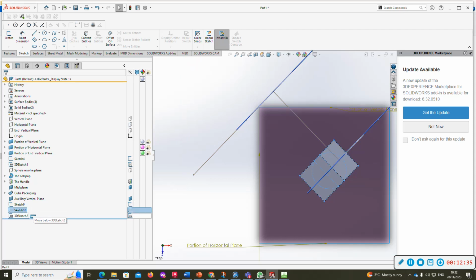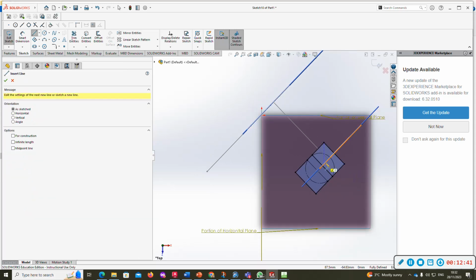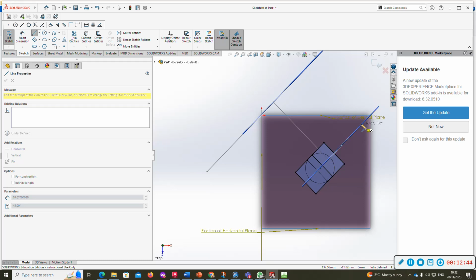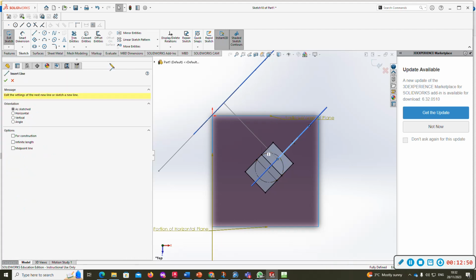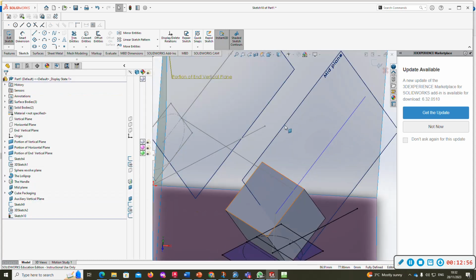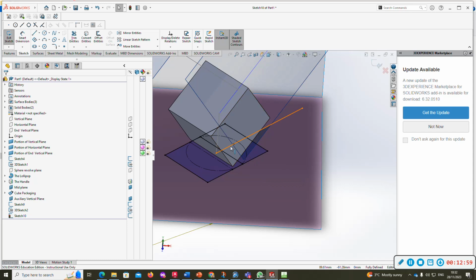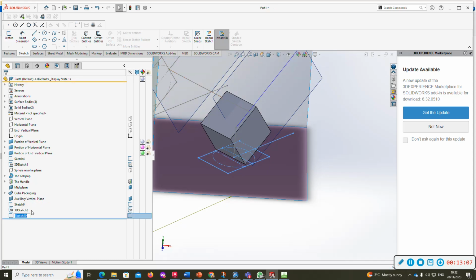So I could drag my sketch 10 below my 3D sketch, edit it, then I could go a line tool out to there, and click OK, do the line again for construction from there to there. Now, we have our plan view, done. So we'll rename this plan view. Auxiliary elevation.